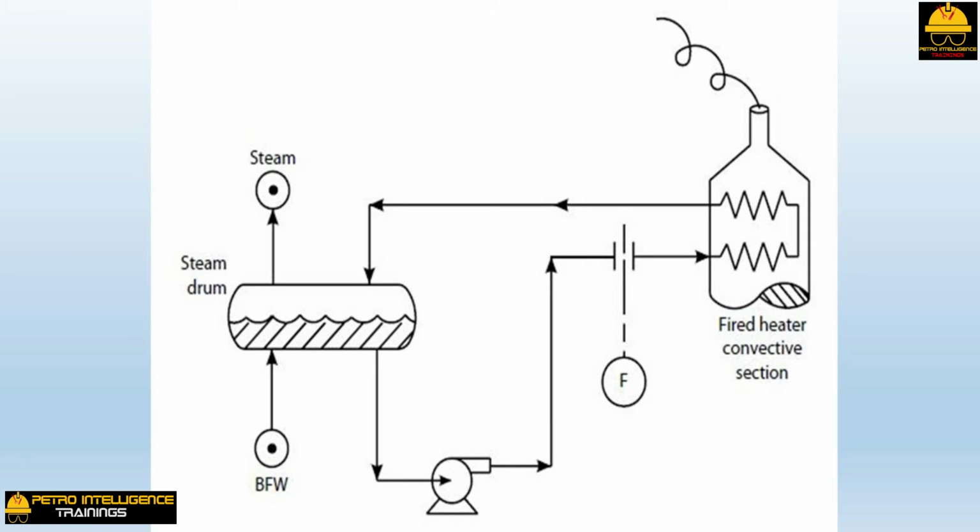This picture is a convective section heat recovery forced circulation boiler. Many process-fired heaters have this feature. Hot flue gas from the radiant section is exchanged against BFW to make steam. A good water circulation rate is 10 times higher than the steam generation rate. Vaporizing 20% of the circulating water is still okay. Vaporization rates above this level will eventually cause convective section tube failures, as will even very short pump outages.